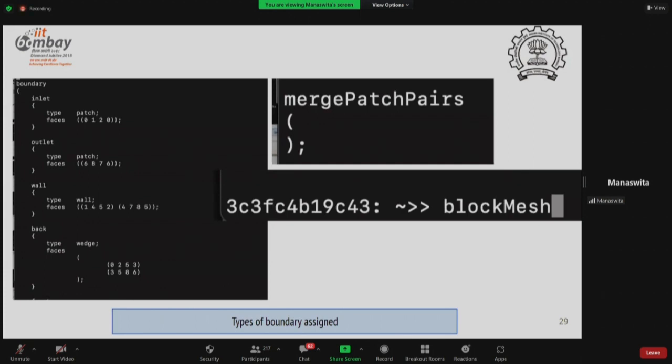This is axisymmetric, right? Yeah. So at any angle, draw some delta theta. Okay, ma'am. And for this pipe, the length and all that remains unaltered, right? Yes, ma'am. So if, instead of doing a full circle 3D pipe, you just draw this wedge-shaped thing, R is not altered, length is not altered. You're just simulating only this delta theta part. Okay, ma'am. I get it.